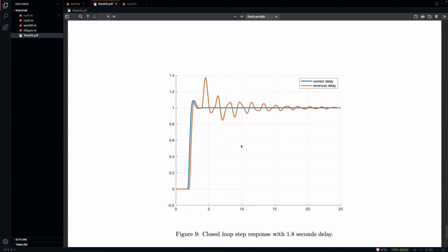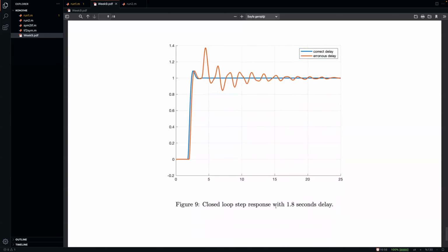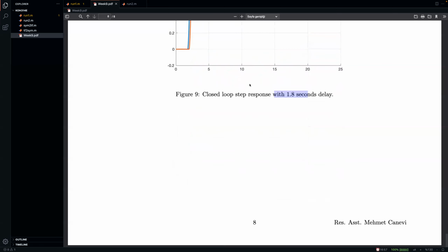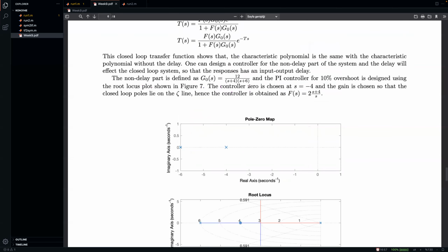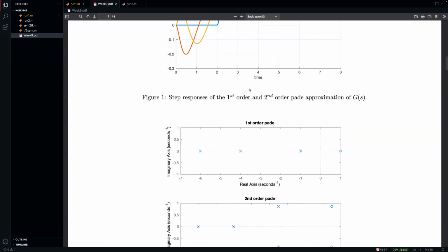So therefore, if you have a correct model in terms of delay, you can go ahead and use the Smith predictor because it has more freedom. It's less restricted, but you can also use the Padé approximation method where you will be quite more restricted due to the model and you're using the model directly without any predictor. So it will be a little bit more hard on that. So this actually concludes our lesson of today.